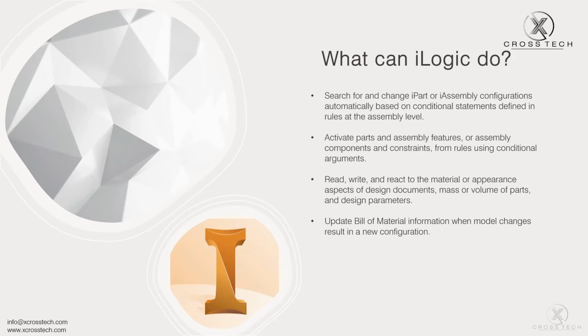It can work within drawing mode, within part mode, within assembly mode. You can have the rules running on open, save, or change of component. You can have the triggers running at different points. You can even have the rules be global, which affect a wide range of different parts and assemblies across numerous different projects.